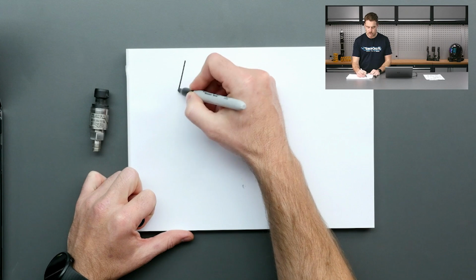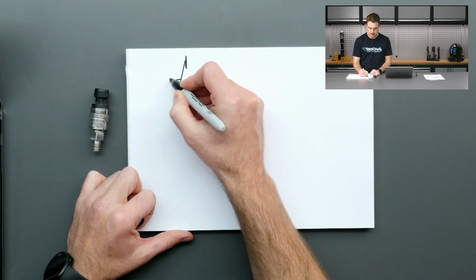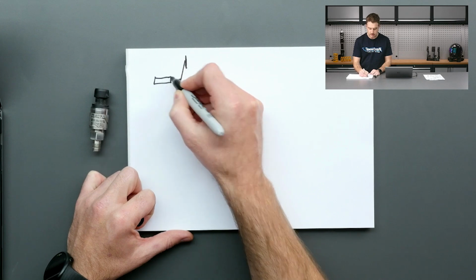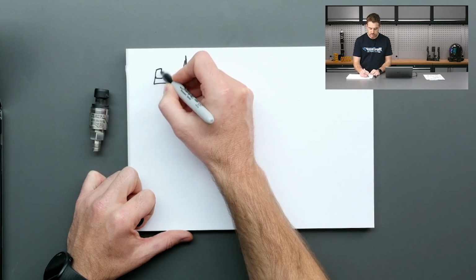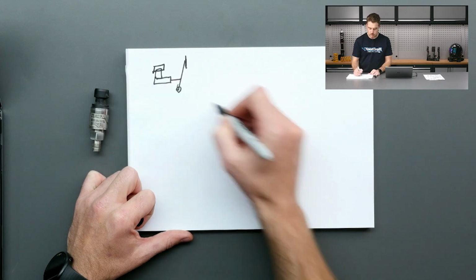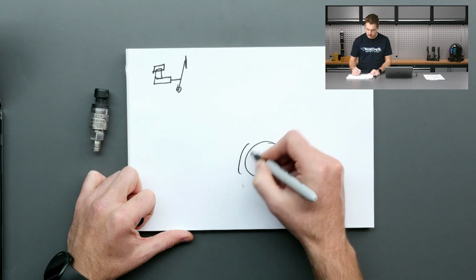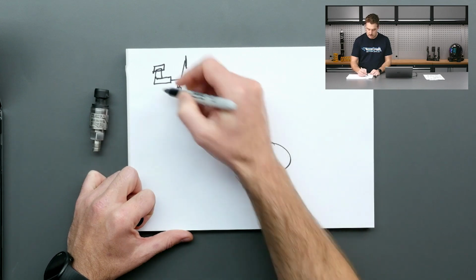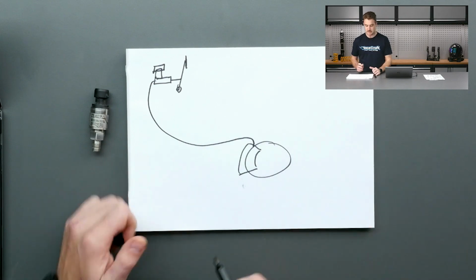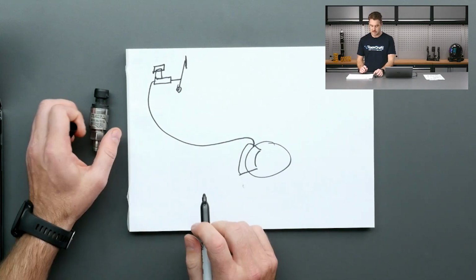So let's say you've got your brake pedal up here. Your brake pedal's pushing on some master cylinder here, and then maybe you've got your fill on the top of the master cylinder there, and this has got a little piston that's pushing in here, and then we've got our brake calipers. So let's have a brake disc, and let's say we've got our brake caliper sitting down here, and we're going to have a hose running from one to the other. So the pressure in this hose is the thing that we're interested in tapping into.